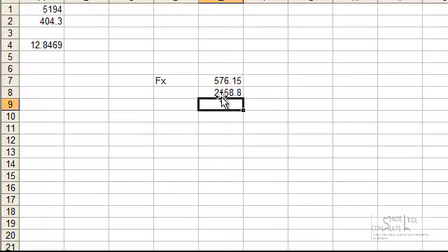So we have very significant resistance. If you look at the ratio to get the factor of safety against sliding, you have it clearly to be 3. So the factor of safety against sliding is 3. So the structure is okay against sliding, and it's okay against overturning.